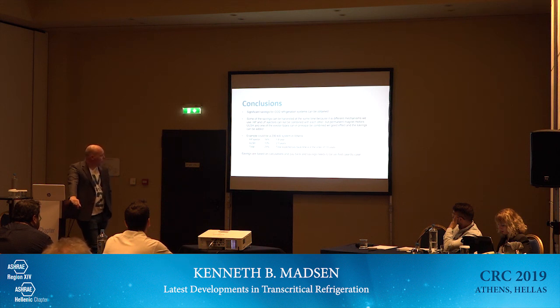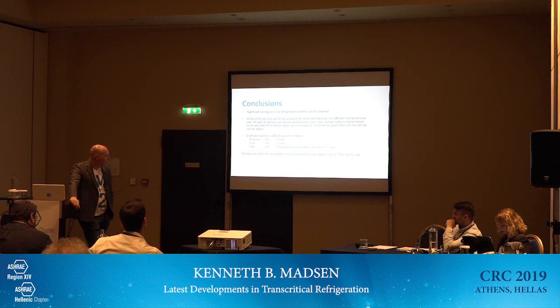So that means if we combine a high pressure lift ejector with ultra-low superheat on the evaporators, then we basically get a total energy saving around 25% compared to a standard booster system. And we get a payback in the order of, let's say, 1.9, let's say 2 years.